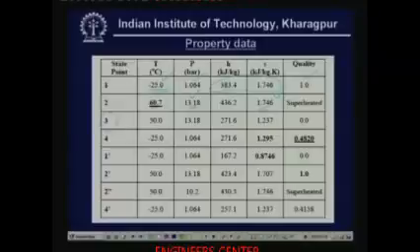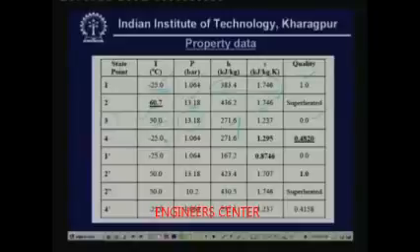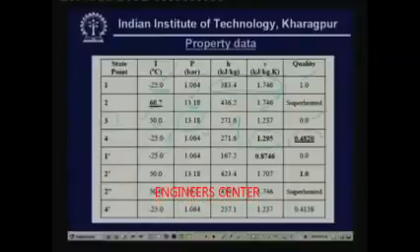Similarly, point 3. Point 3 is the exit of the condenser. We know the temperature and we know the quality. So, find the pressure, find the enthalpy, and find the entropy. Point 4, okay, it is the exit of the isenthalpic process. So, the enthalpies are same at point 3 and point 4, which is known to us, and we know that the temperature is minus 25, which is same as the evaporator. Pressure is now also known to us. So, from this we can find out what is the entropy, and you can also find out the exit quality from these enthalpies.